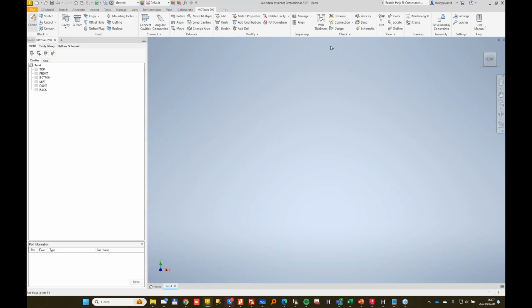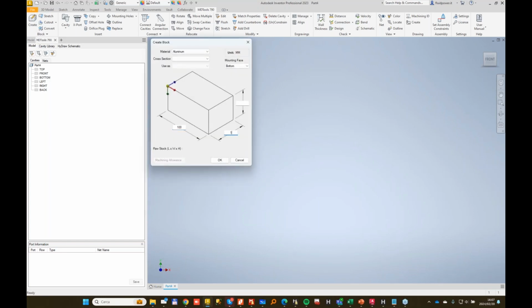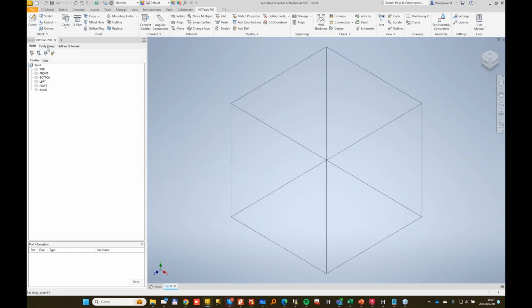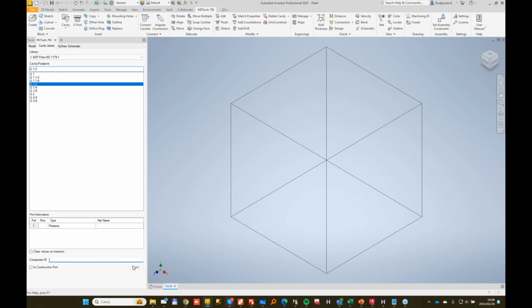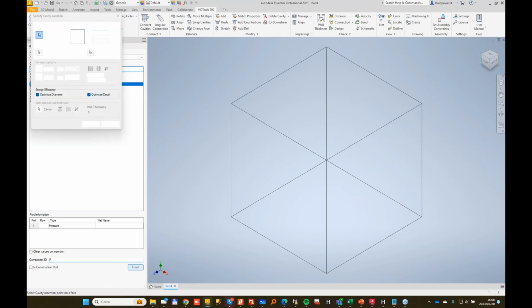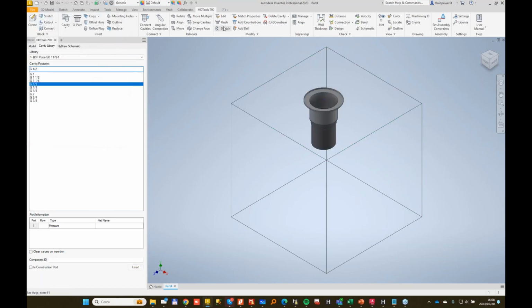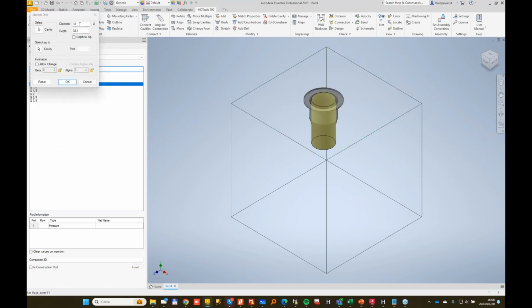Now if I create a new block, and we'll do some tests with it, I put just a BSP port, a G1x2 BSP port, call it port number P, and insert it in the drawing. And maybe in my drawing, I change this diameter to 50.